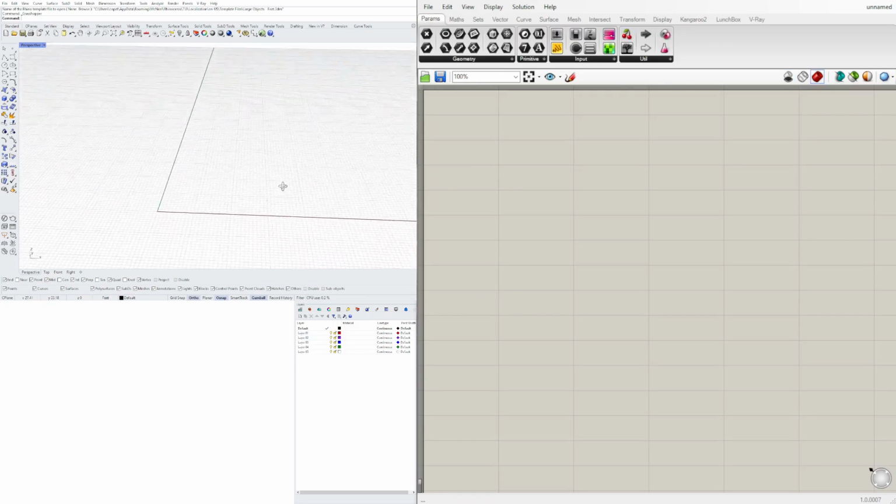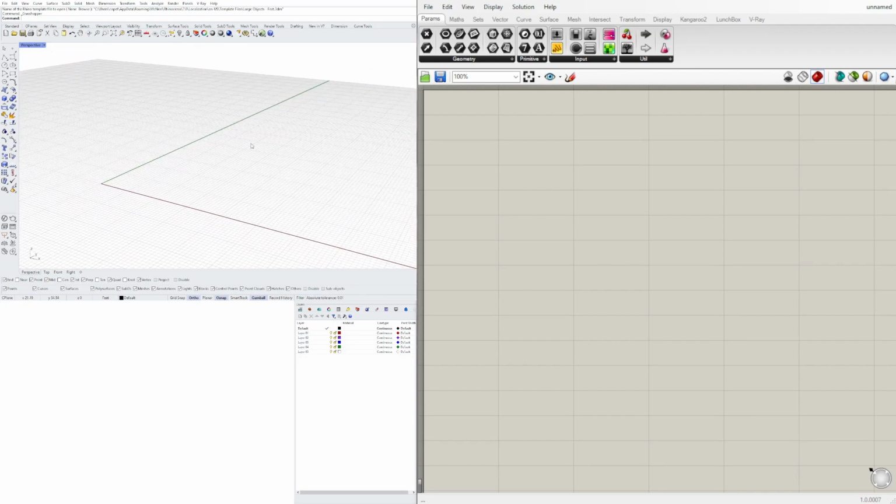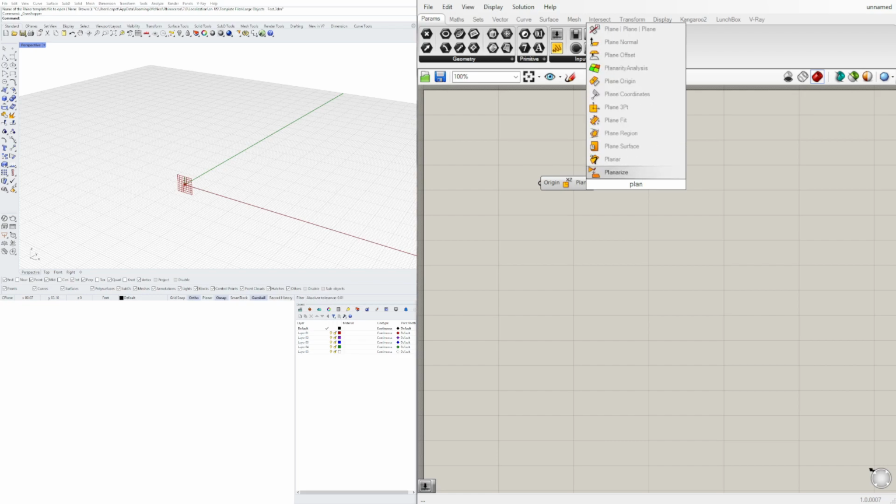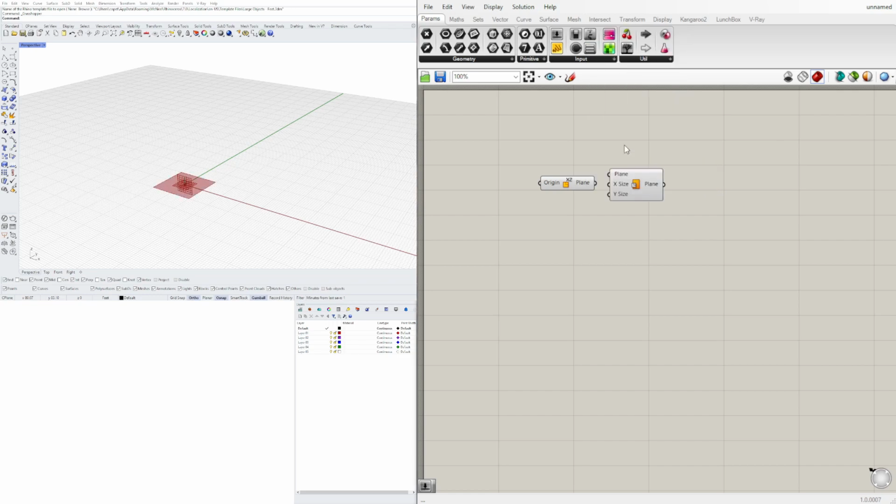So to start, we're going to bring in 3 different planes. So we'll bring in a reference plane. We're going to use the YZ plane, or we can actually use the XZ plane. Now, let's bring in a plane. When we bring in the plane surface, we can use this plane to plug into that. And now we can plug in an X and Y size. So go to 25, go within the X and Y. And let's actually create a different one for the X.